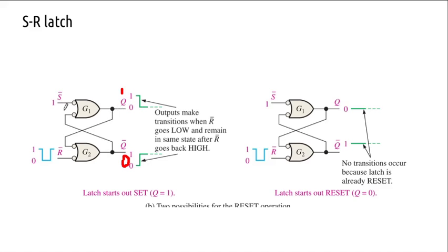Just spare some time. So that is 1 and I am having a 0 here. So I'll feed back this 1 from this point to here, so 1 and 1 makes it 0, and again I feed back this 0 here, that is going to make it set. Now I am going to apply a momentary 0 on this R, and the set is still remaining high. It is the set condition. The 1 here is fed back here, and the output Q bar becomes high.